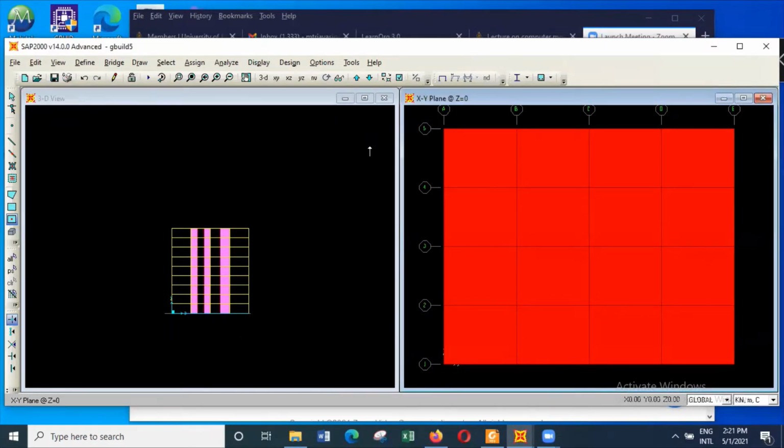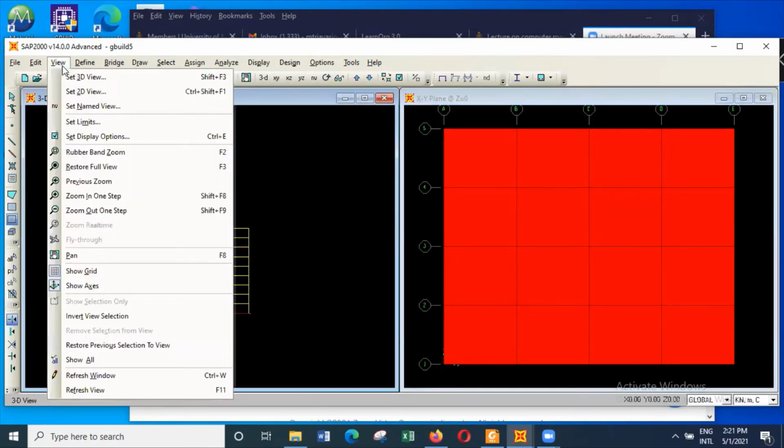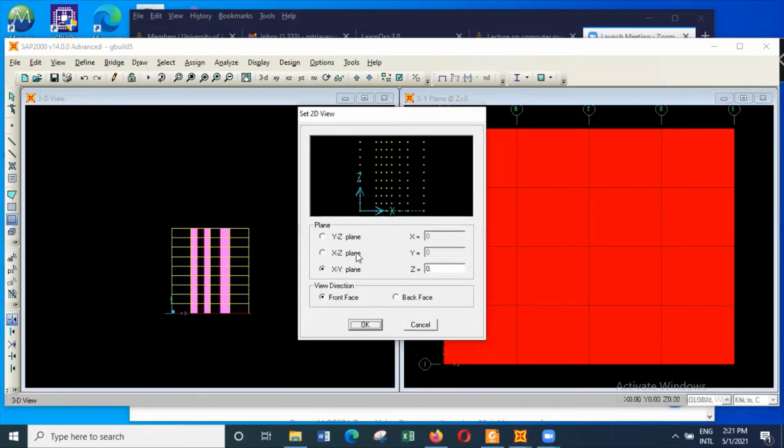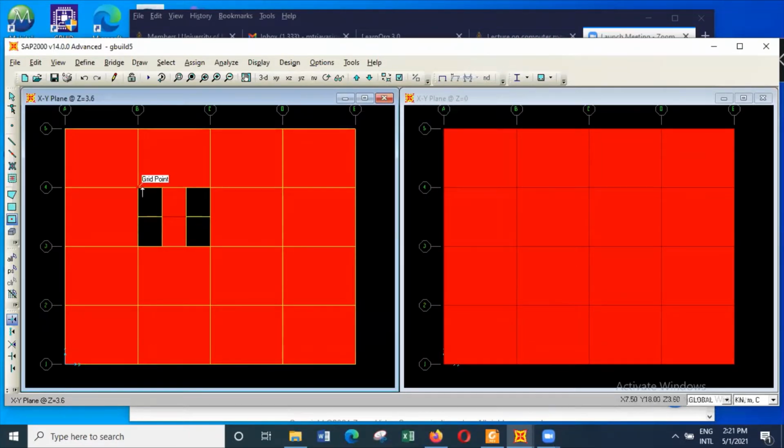So what I can do is look at the ground level. Here you can see the floor level coordinates: 0, 7.5, 9, 10, 12.5, 15. And here you have another shear wall, it is 1.875. So if I divide this way into 6 parts, and this way also into 6 parts, then I can subdivide the raft into 6 segments in each direction.